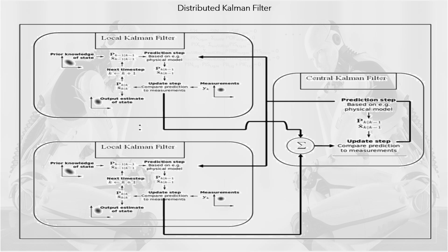The operation of a DKF is generally based on the integration of local filters and network communication strategies. The main components are micro-Kalman nodes. Each sensor runs a shrunken, local version of the Kalman filter to generate a preliminary estimate based on its own data. Consensus filters, communication algorithms that allow nodes to agree on information matrices through repeated interactions with their neighbors, and information representation. Many DKFs use the Kalman filter information form, based on the inverse of the covariance matrix, since information contributions from multiple sensors can be easily added together in a distributed manner.